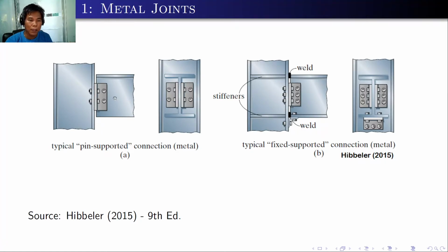Aside from the angle connection that you can see here with the bolts, there is an added welding at the top plates and the bottom plates. Also with another support here, an angle connection with the bolts. And aside from that, the stiffeners are added along the line of the top plates and the bottom plates. This will make the connection moment resistant. So it will hold moment.